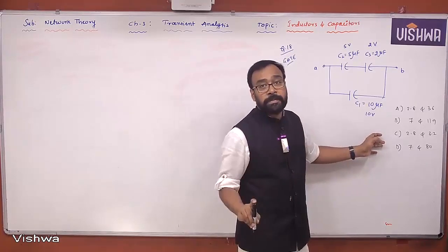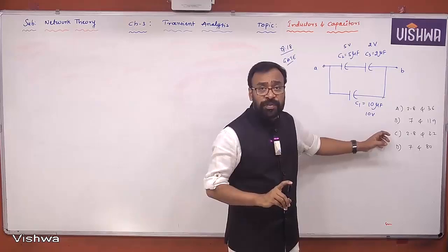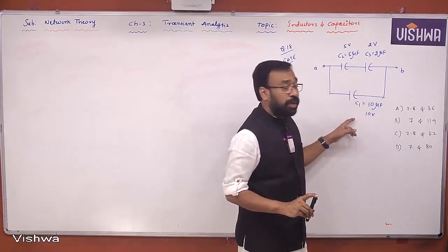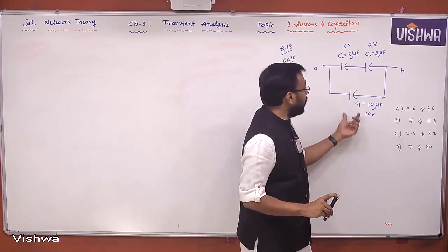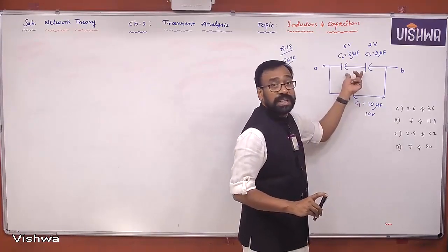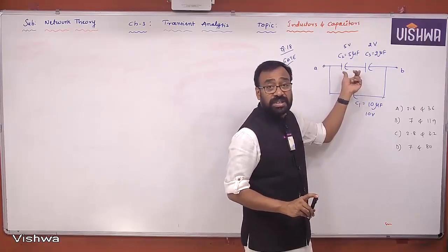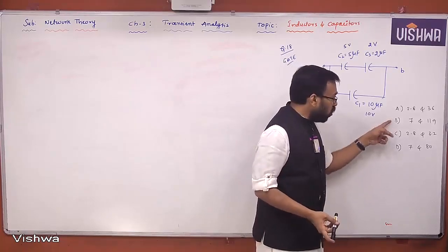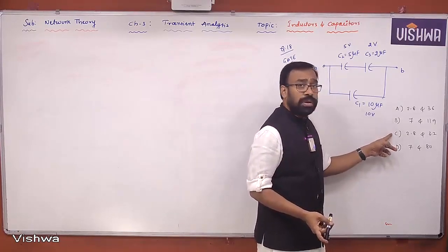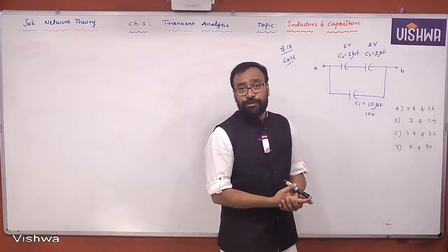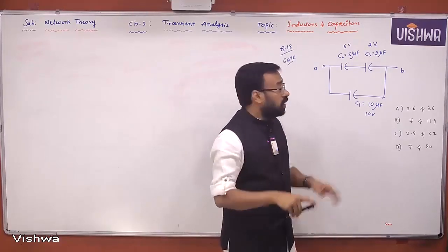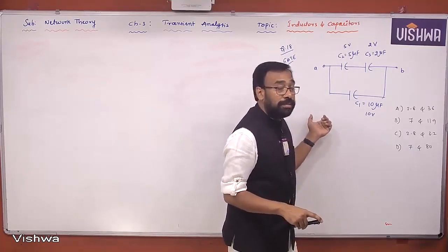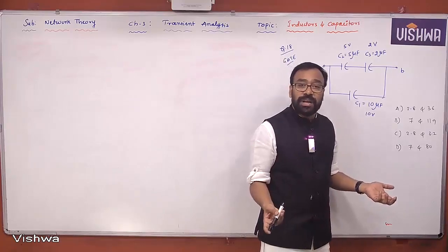No doubt in that. Understand all of you? So what will I do? Tell me all of you, from the 4 options, first I apply 7 volts. Let me see if any capacitor is damaged or not, because maximum safe voltage is 10 here. If you apply 7 volts, this is safe, but we have to check whether any capacitor is getting damaged or not. Understand all of you? Okay. If any capacitor is damaged, then this 7 volts is not applicable. So 2 options are ruled out. Then the other 2 options are left over. Then obviously 2.8 is the safe voltage. For that 2.8 volts, the total C equivalent you can calculate. Now Q is equal to C into V. You can multiply them. You will get the charge corresponding to that particular maximum safe voltage.